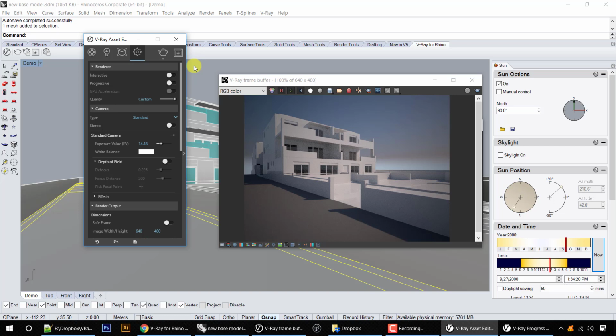But anyway, when you're ready to render, you can click on quality here, and there are different outputs. Basically draft is fast and low quality, then medium, high, very high. If it's a PDF, you might just go medium. If you're going to print it, you might go high or very high. But again, the amount of time it takes to render is going to increase exponentially. It's also going to increase with the more reflective materials and the more objects you have in the scene, et cetera. So those are things you're going to have to watch out for.